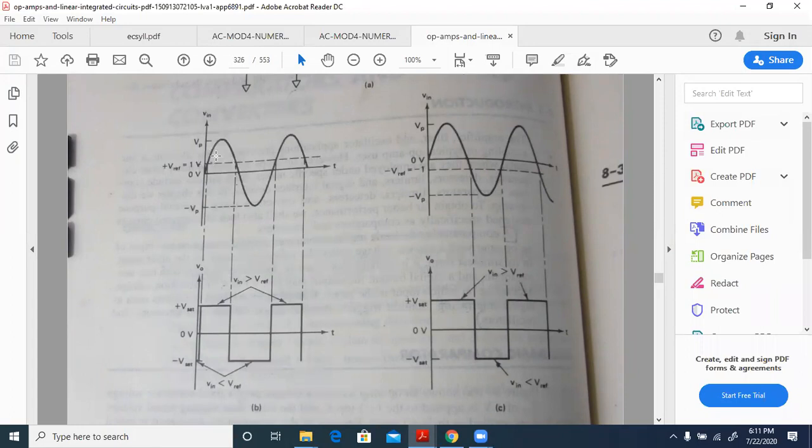So now, if we consider this as 2 volts peak to peak, then at exactly the middle of this, it will be 0.5 volts or 500 millivolts. So you have to pull that down, and only for the small portion over here you will have the high, and for the rest of the portion, from here till here, it will become low.